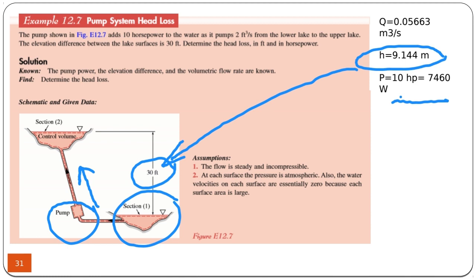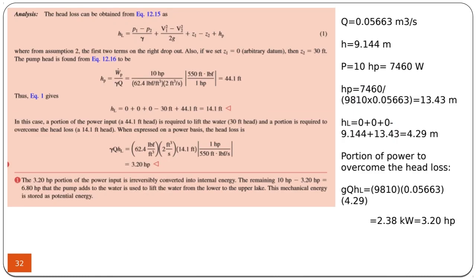So we always start with the energy equation, but this time it has a pump term instead of a turbine term. The pump term is positive on the left-hand side, but becomes negative on the right-hand side. So here we leave the loss term alone. All the rest are the same, except there is an inclusion of the pump term.